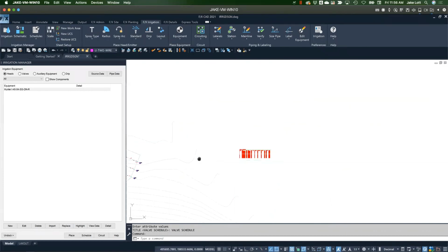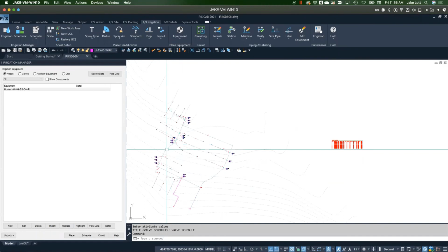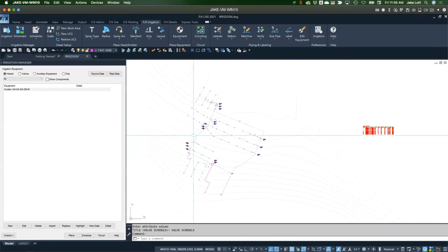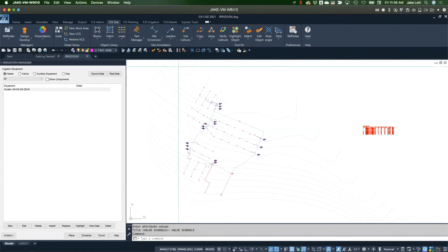Past this, let's go ahead and really quickly account for elevation, because that might totally change things, right? So if you've gotten an elevation plan and there is elevation set to each one of those polylines, we've got a very cool tool, our spot elevation tool, that allows us to place a grid.